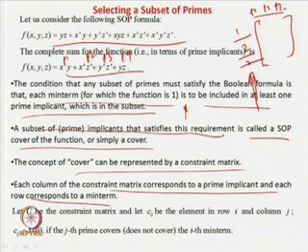Okay. So we are representing it by a constraint matrix. Here all the prime implicants are listed, and 1, 2, 3, 4 are the min terms. So here it can be of the order of 2 to the power n. If the expression is 1, then all the min terms possible are there, all terms like 0, 0, 0, 0, 0, 1, up to 1, 1, 1, 1, are all min terms. Then this will be very long and exponential. And then we put a 1 over here if this prime implicant actually covers this min term. This is the idea.